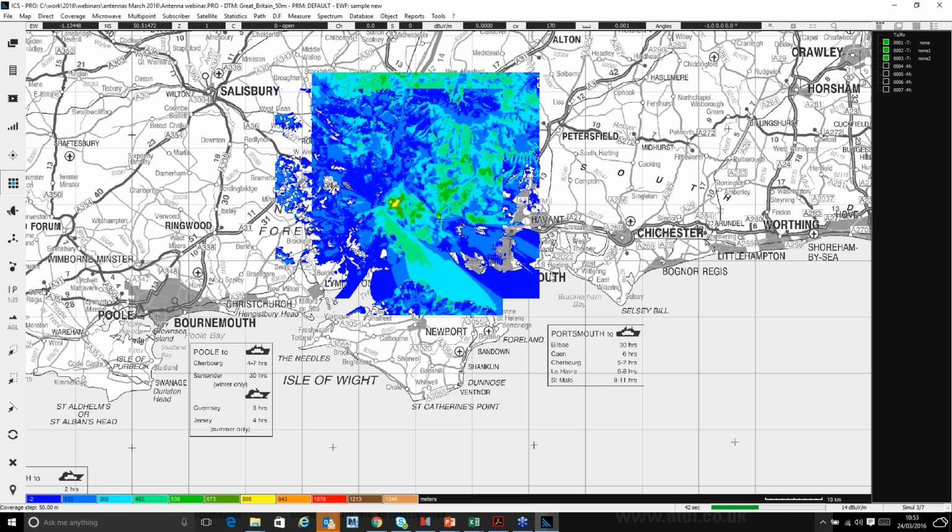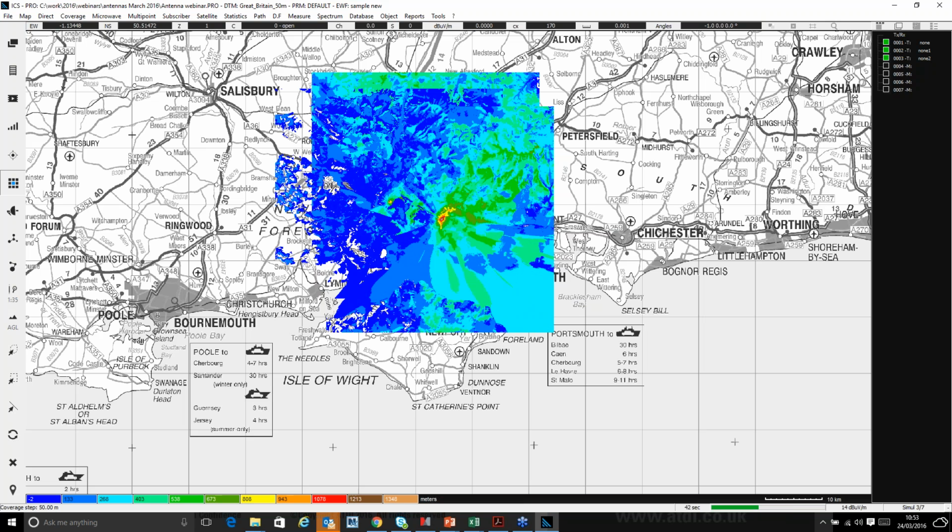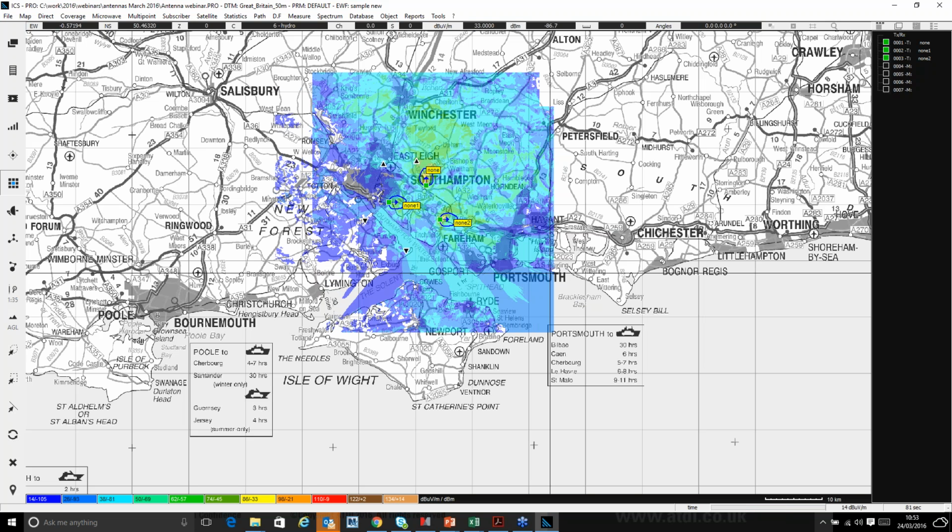One thing perhaps just to mention at this stage is to be careful with the tilts, because often you'll find, particularly with the electrical tilts, that the antenna patterns have this information built in. So don't obtain a pattern with, say, an included 4 or 5 degrees down tilt, and then add an extra tilt into the station, because you'll effectively be double counting, as it were.